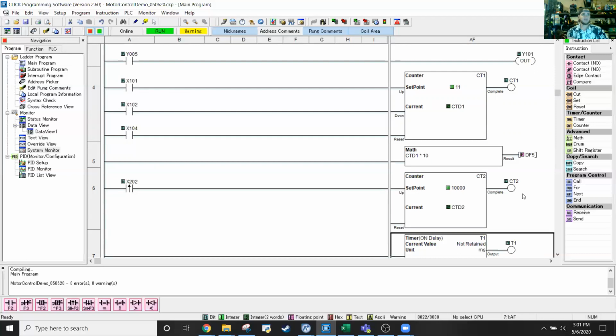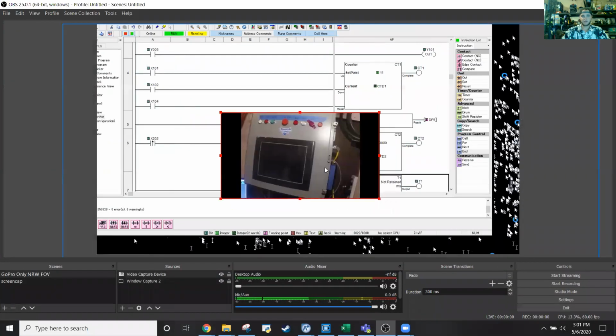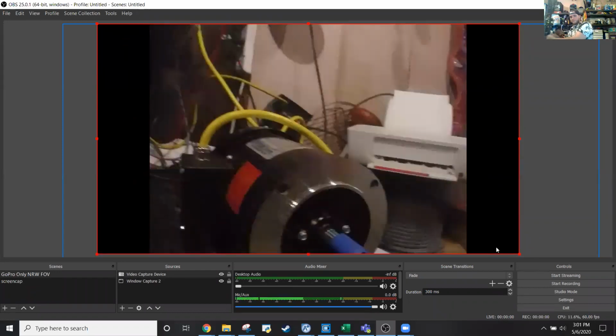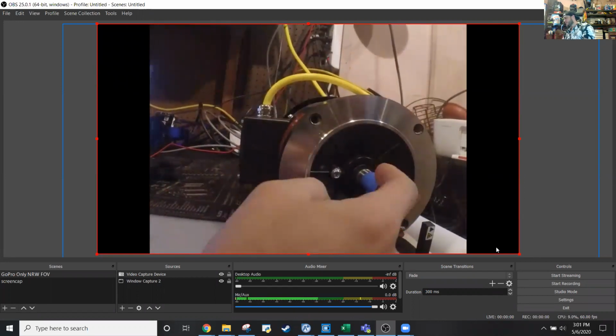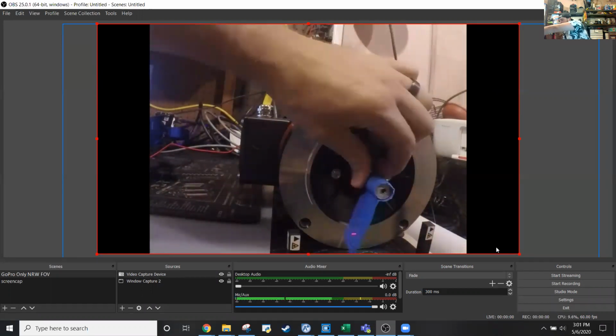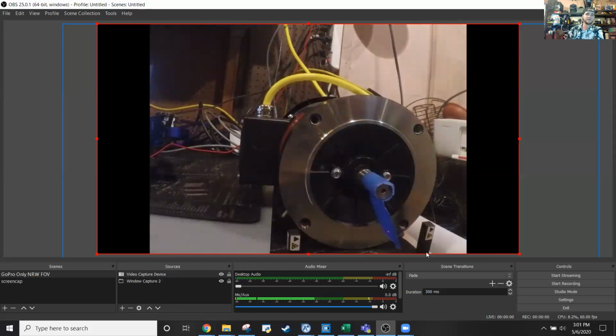And so if we were to, let me bring over the camera again real quick. Change my view again. So right now, we just have one little flag off of this motor. If we put another flag off the top of this shaft, then the beam would get broken twice per second, right? And you'd have a 2 count encoder. And you could do it with 4 flags. Probably because of the physical limitations of this system, the most we're going to get on here is 4 flags.